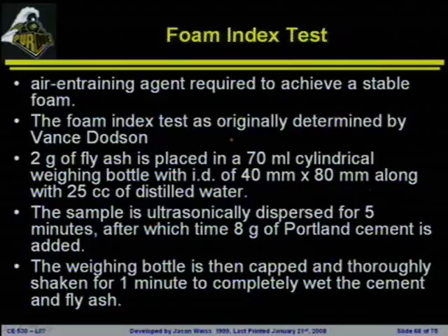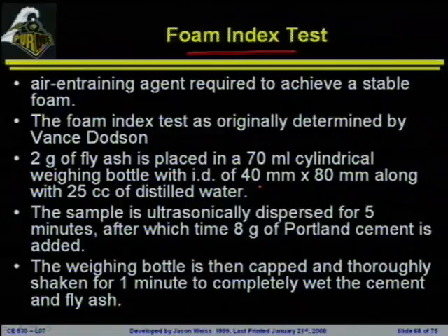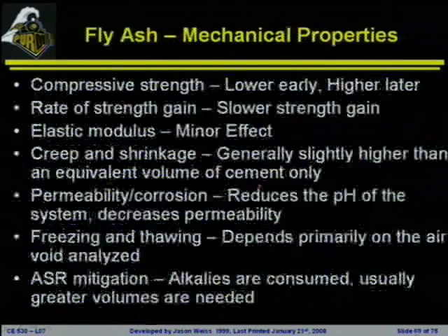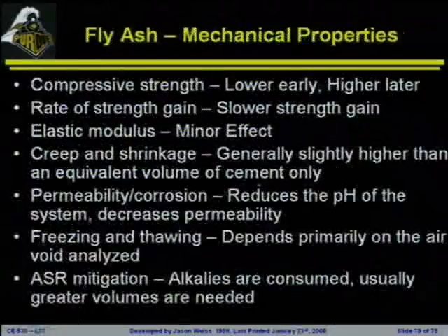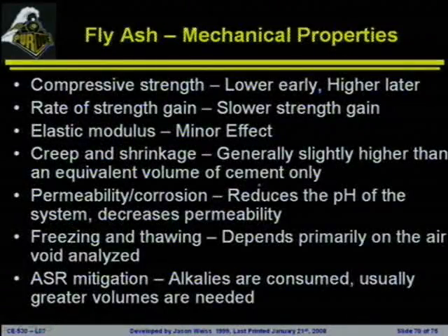One other test that you can do to see its ability to interact with air entraining admixtures is a foam index test. You can read through here, but the basic idea is you take a little bit of the fly ash, a little bit of the air entraining admixture, shake it up, and see how long it keeps a nice frothy head on the fly ash, cement, water, air entrainer admixture, and that tells you a little bit about how much carbon is in the overall material. So I've got all the steps here, so you don't necessarily have to go out and look for it, but I'm not going to go through that in real great detail.